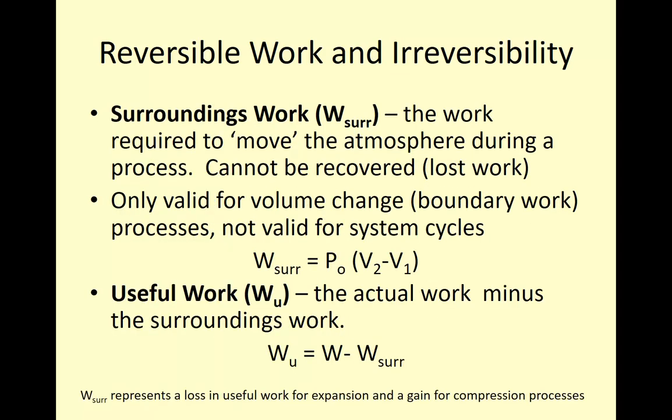So surroundings work is the work required to move the atmosphere during a process. And this is work that cannot be recovered. It's considered lost work. So if we think about a piston cylinder device, and we're expanding the gas inside that piston cylinder device, there's some work that has to be done to move the atmospheric air out of the way. So the surroundings work is considered not wasted work, but work that's lost during an expansion process because our system has to work even harder against the atmosphere in order to expand. And then during a compression process, it's actually considered a gain because the atmosphere is helping to compress the gas that's inside of our cylinder.